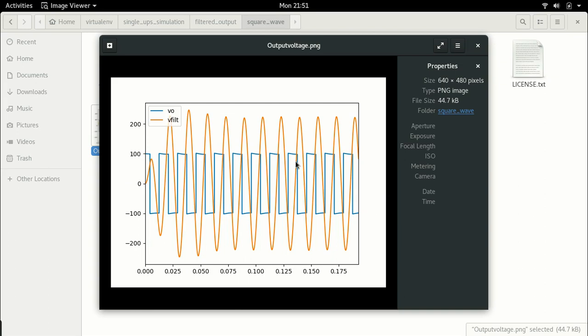There are things like space vector modulation and things like that. Those are different. I will talk about that maybe in a future lecture. But when you use square wave modulation, this is the burden that you must bear. That is, very large filter elements in order to achieve a sinusoidal voltage waveform. So this is going to be the justification for using pulse width modulation, which I am going to do in the next lecture, which I hope will be tomorrow.